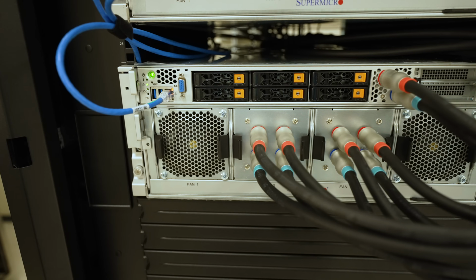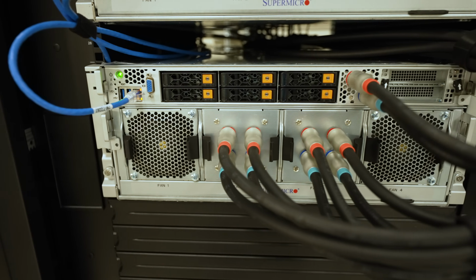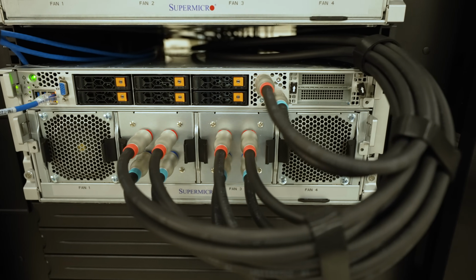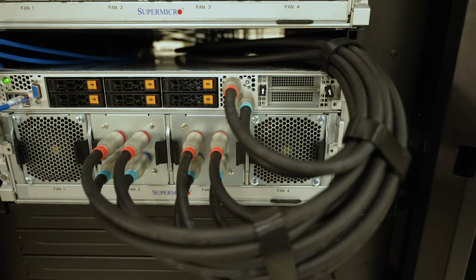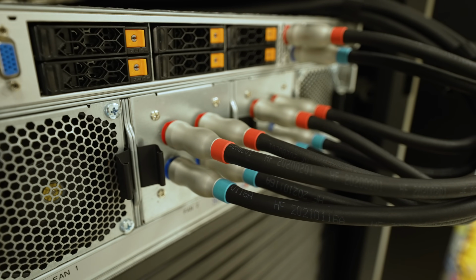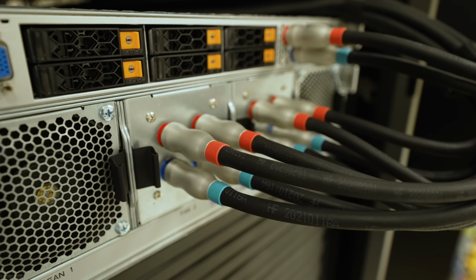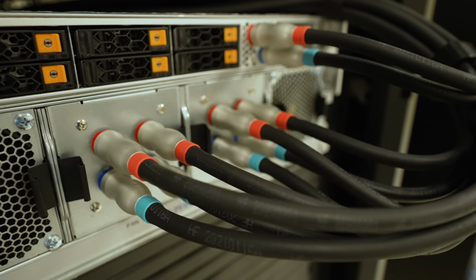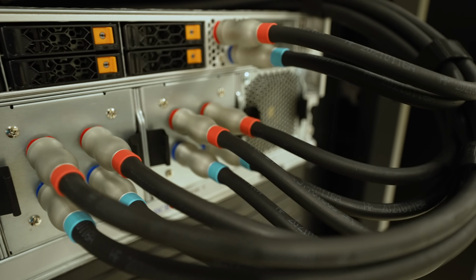All right, the third one is probably the one that most of you that are watching this are most familiar with, and that's really the direct-to-chip cooling. And so here what you basically have is you have liquid that is pumped to a cold plate that sits on a CPU or AI accelerator, GPU, something like that. And then you do the chip to that cold plate to the liquid heat exchange, and then that liquid is brought out to some way to expel the heat out of the server.